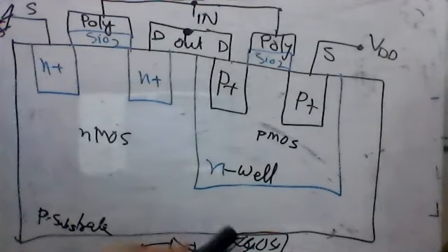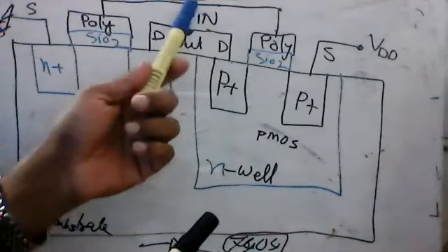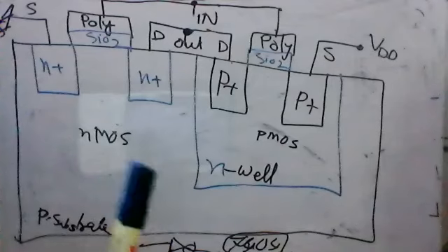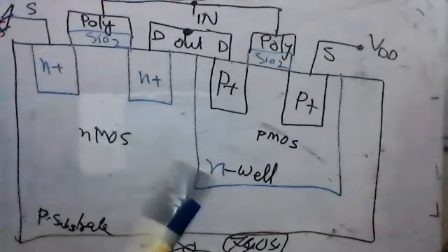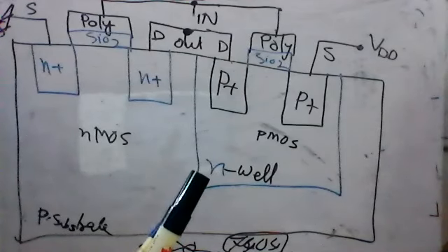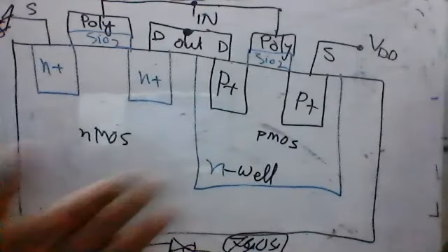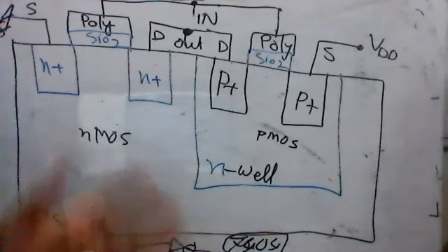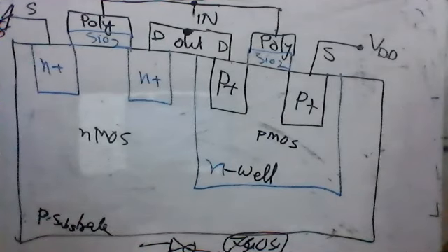There are 6 inverters inside, and for the 6 of them, two pins each are needed, 1 2 3 4 5 6, and then 7 is here, and then 8 9 10 11 and 12 13. There are 6 inverters and 14 is VDD. So this 14 is common for all the inverters. We'll see that later on. We'll make the real circuits, but anyway, this is the very simple diagram where by using one CMOS we get one inverter. But as I mentioned, this is a side view.